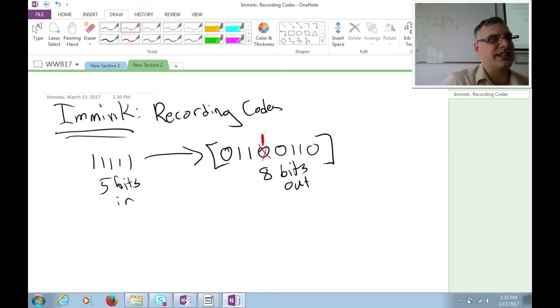So if I have a communications channel that produces fairly few errors, this is a great way to do error detection, because I would actually have to make 2 errors, and not just 2 errors, but 2 very specific kinds of errors, coupled errors, in order to make the kind of mistake where the code word would balance again.